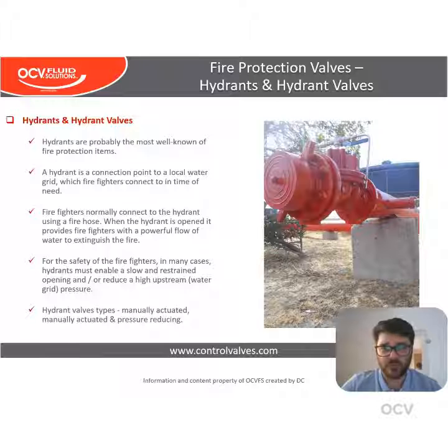Now we get to hydrant valves. So a hydrant is probably the most well-known fire protection item. You can see one on every street. And basically a hydrant is simply a connection point to the local water grid to which firefighters connect when they need. They usually do this using a fire hose. And for the safety of the firefighters, a lot of times the hydrant needs to enable a slow and restrained opening, or simply reduce the high water grid pressure to a set downstream pressure.